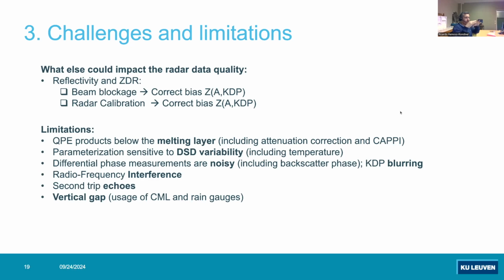So you see in the spectral domain the signature of rain, for example, and the signature of a radio frequency. So you can filter this, and then you integrate, and you have a reflectivity which is less contaminated by interference. So that's more or less a processing methodology that you could do in the spectral domain, so before you integrate.